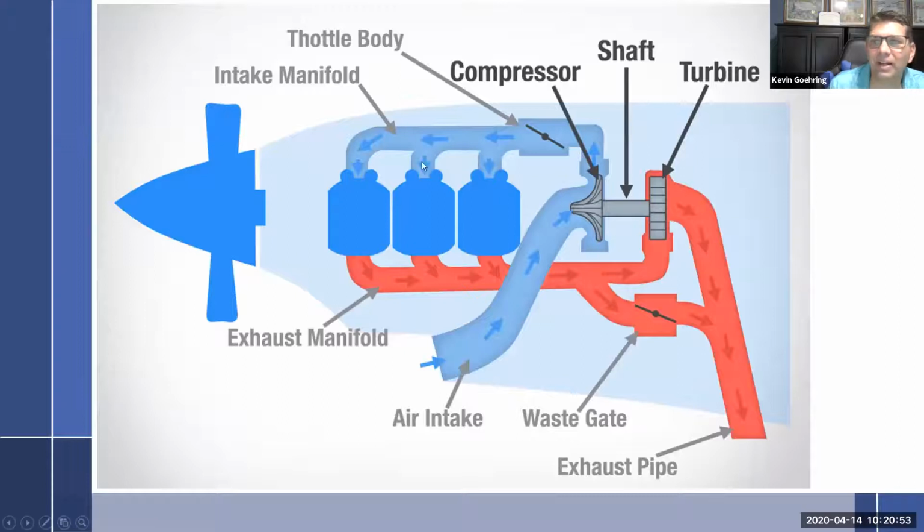So that was bad enough that we have these two that we're trying to deal with, but heaven forbid you actually touch the prop control, which changes the pitch of the propeller, which now slows the engine down. And so now you have an engine that just changed RPM. Well, that's going to have an effect on things.